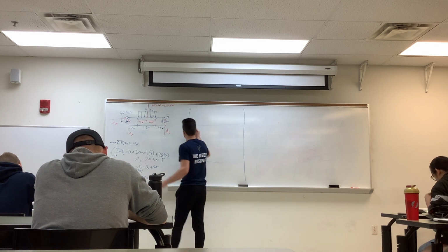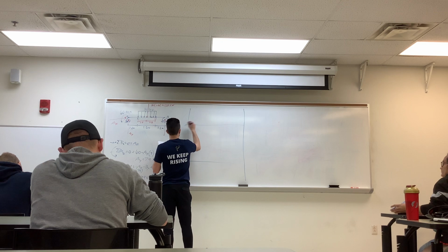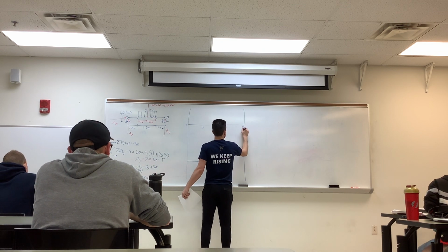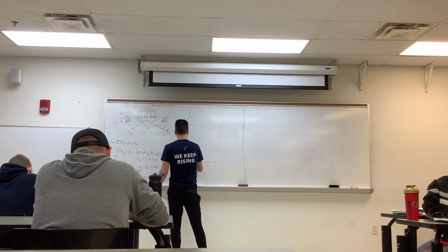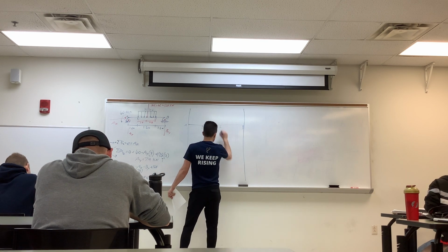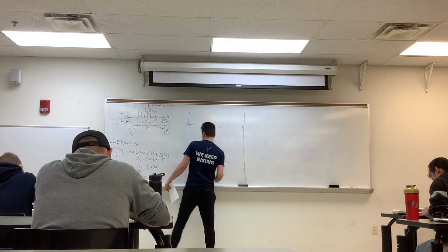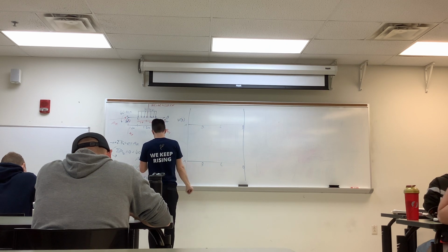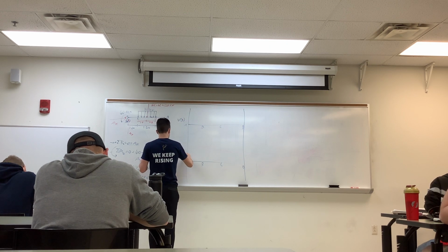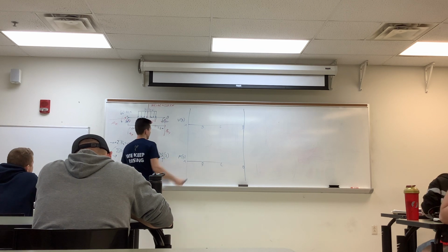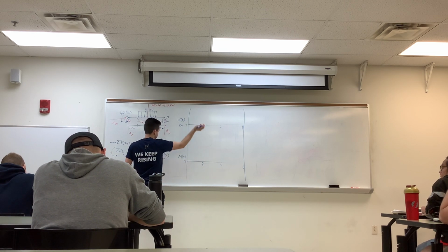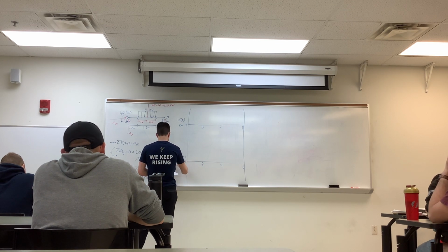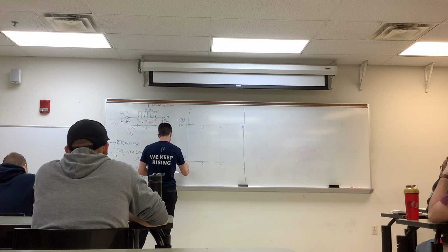So we have this as point A, point B, point C, point D, and then similarly A, B, C, and D. So first diagram is your shear diagram, and then your moment diagram. Units for the shear diagram are all in kilonewtons, so you don't have to put them all throughout the whole thing. And units for the moment diagram are kilonewton meters.